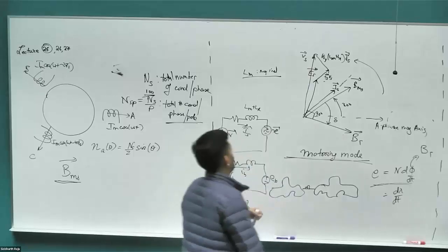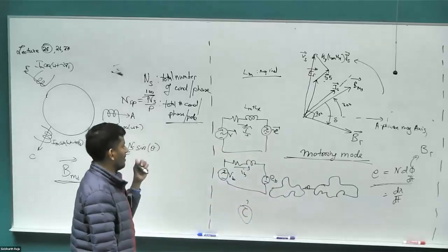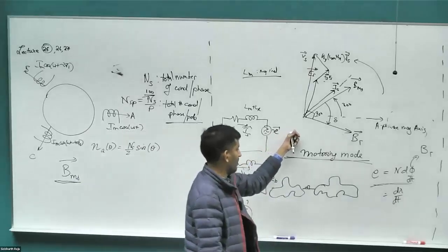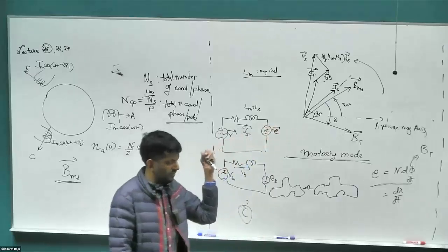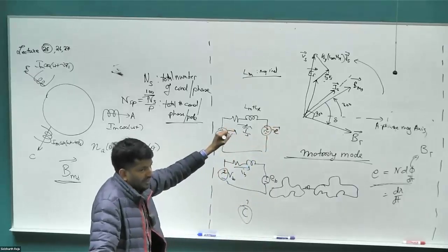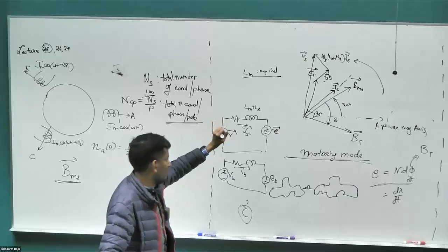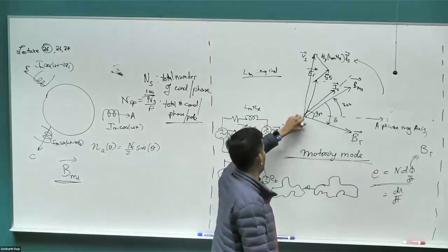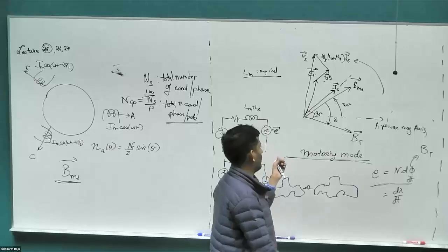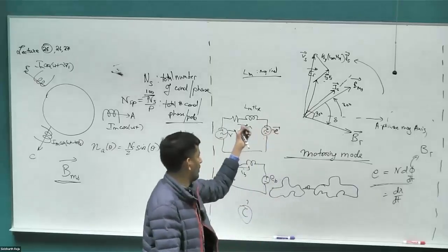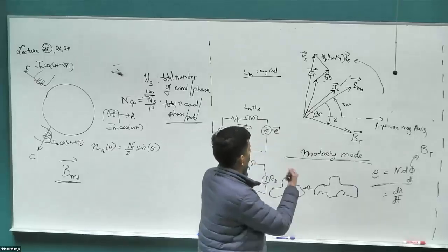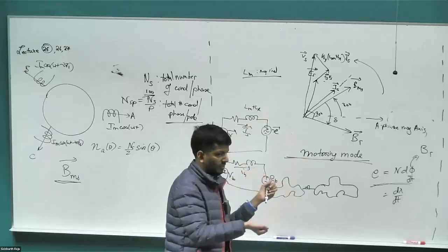So we have space vector. Right? So there is a relationship between space vectors and phasor diagrams that you have drawn for AC circuits. If you take the space vector and take a screenshot of it at any particular time, I'm drawing it here in the drawing, since I can't draw something that's rotating continuously. It looks as if it's a fixed value, but in reality, when you visualize this in your brain, it should all be continuously rotating. That's what space vectors do.